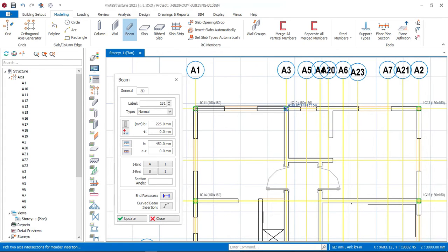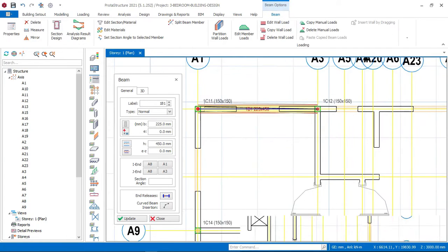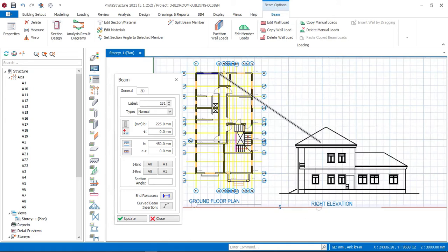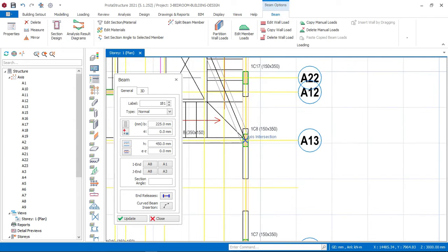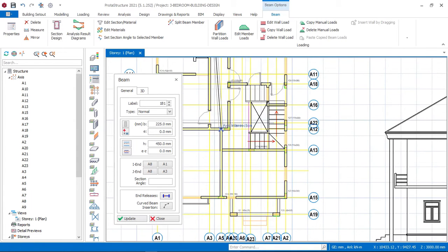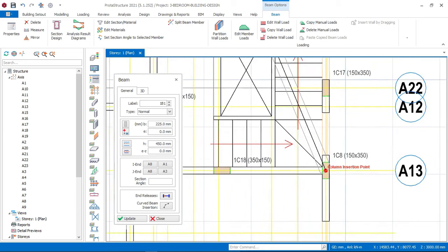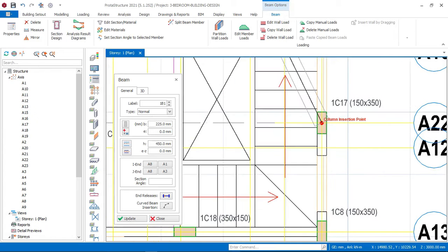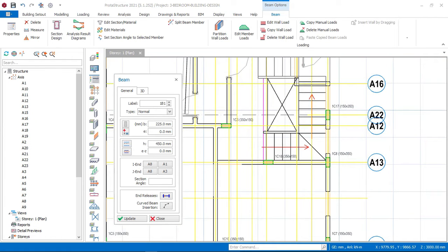Now this place is a 150 wall. As you can see that this is like a bungalow having a pent floor. So because of that right now, they used 150 millimeter wall for all their block wall sizes. As you can see that all the column size width is already 150, as you can see there. So with that right now, I will now go and reduce my width of beam to 150, and then click on update here.